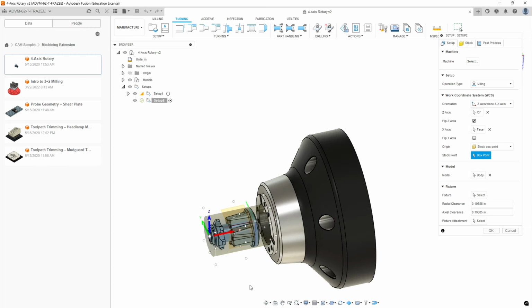It'll use tool diameter, dynamic work offset, and dynamic tool length control. So you could literally cut something off center. But if you're close to circular, you're going to get better results accuracy-wise if it is lined up with the center line of the rotary axis.